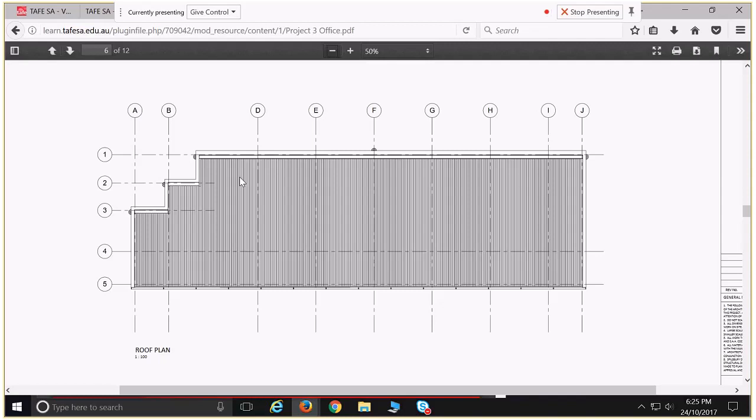And then we can only put them together in banks of 2 before we need another 600mm offset from that bank to another bank for access around. But we can create that bank all the way along until 600mm from there, and all the way along like that. And then it's just a matter of dividing that up by 750mm all the way along, and we get X number of panels in there.